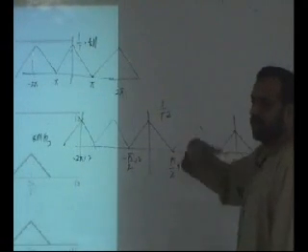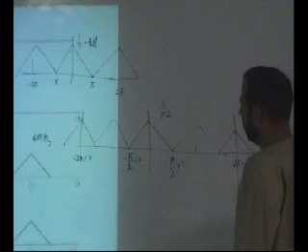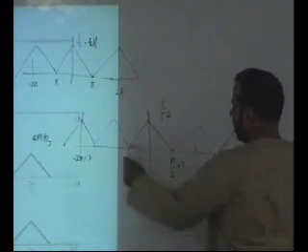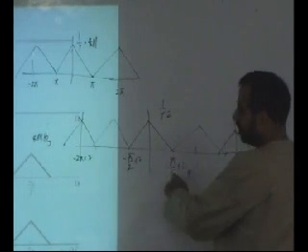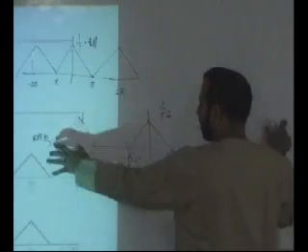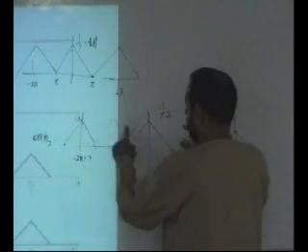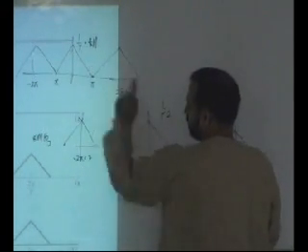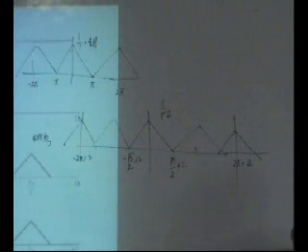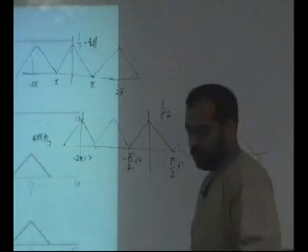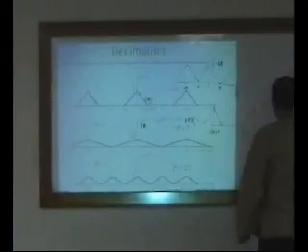If you are throwing away every other sample, it is decimation by 2. You are multiplying your frequency axis by that factor and then making extra copies of the spectrum to make it look like this. This is what decimation is all about mathematically, and it is shown here.